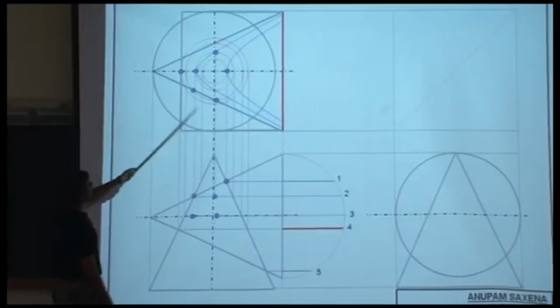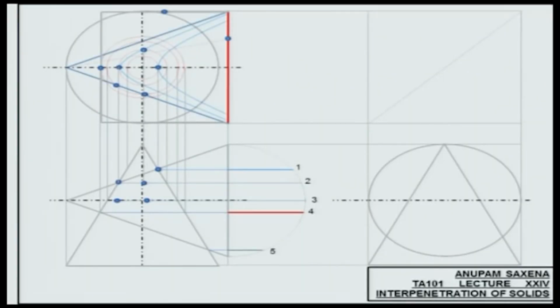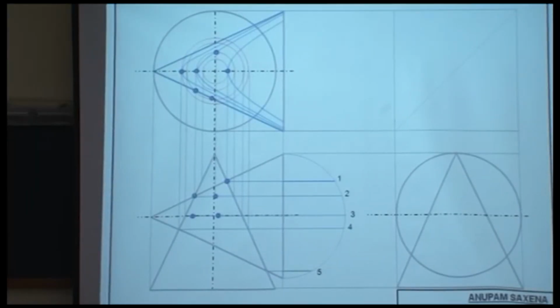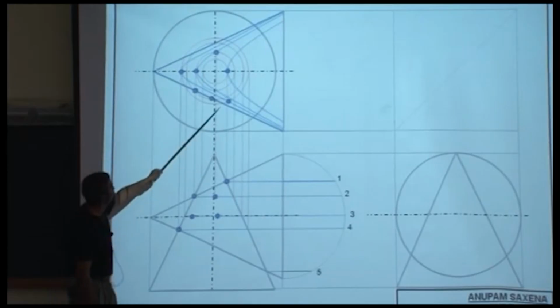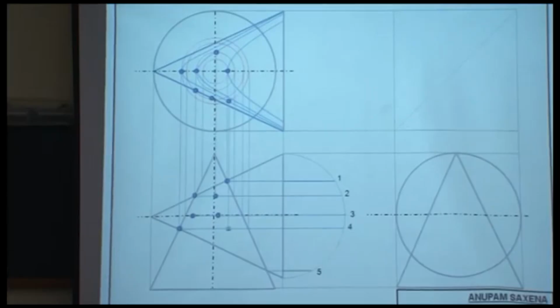Okay, divide this edge into equal number of parts, that edge into equal number of parts. Okay, start joining the lines, find the intersection points. You'll have 4 intersection points in all, or 4 points lying on a hyperbola in all. Draw that hyperbola, draw the mirror image of that, find the intersection between the corresponding circle and the hyperbola. Okay, so of course one point will be here and the other point will be here. And of course, there would be a corresponding point at the top. Okay? And the fifth point is quite obvious. I mean, it has to be lying here.